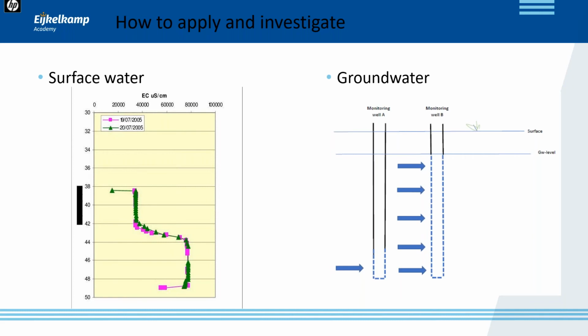In those kinds of wells, sometimes so-called packers are used, with which you can isolate parts of the screen from the rest of it to make your measurements more accurate. It prevents mixing of water from different depths.